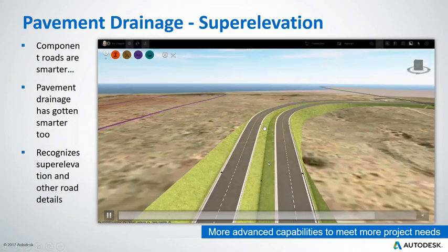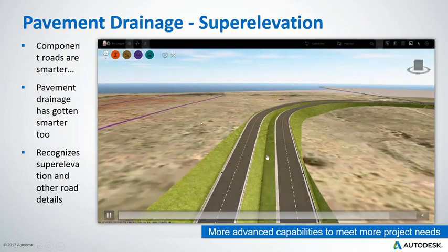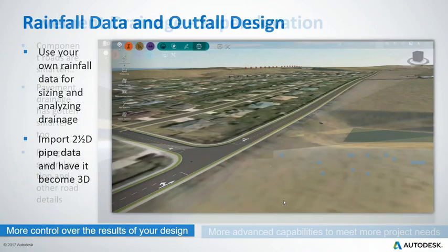And also places inlets in the median if need be. If this median is functioning like a channel, drainage channel, then also will place the necessary inlets and connect them with the main drainage network to cater for the flow.